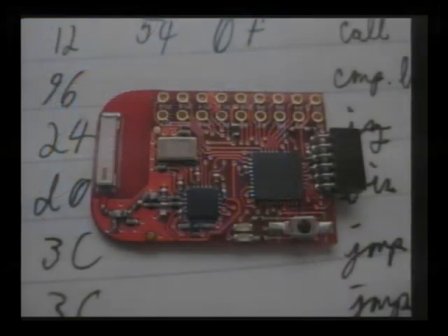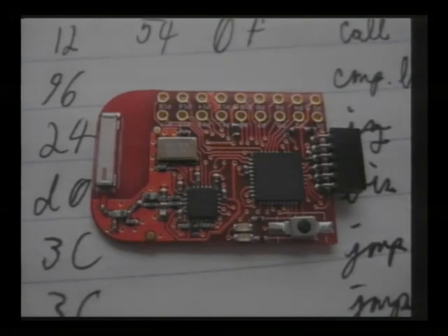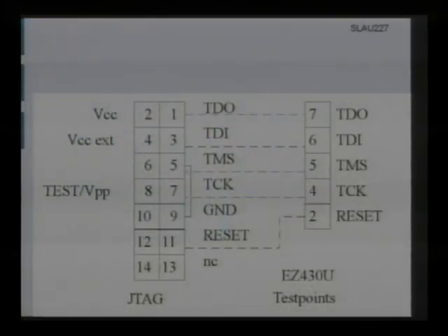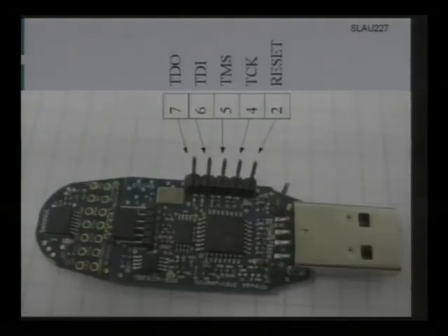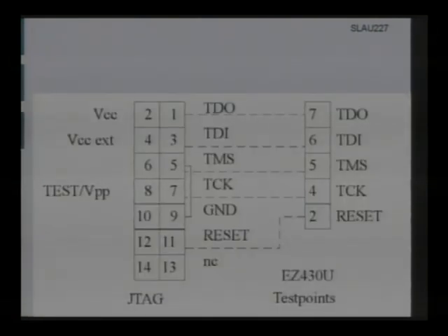Another target board that you can have, the intended route for you to move up with TI, is this. It's a 2.4 gigahertz wireless sensor node, powered by the same connector, and running firmware that they supply for you. Now on the EZ430, if you read the documentation, you'll find the JTAG pins, and they exist as test points on the side of the device. So if you build an adapter, you plug it up, you can then hook up another in-circuit debugger from TI, and you can dump all of the code from the target device. You can also replace the code.